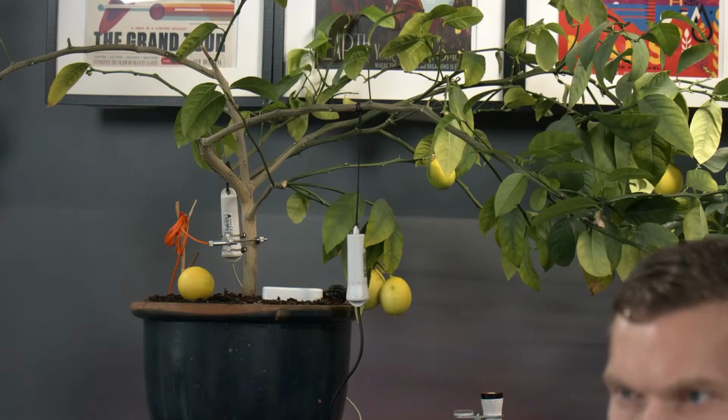1600 steps. So the measurement precision is around 3 micrometers. It's 5 millimeters divided over 1600. And that's sufficient to see the slightest changes in the water status of the plant. So we are using it in cucumber, and in tomato. We have done amazing work with it in determining blossom end rot appearance and grey mold appearance on tomato.